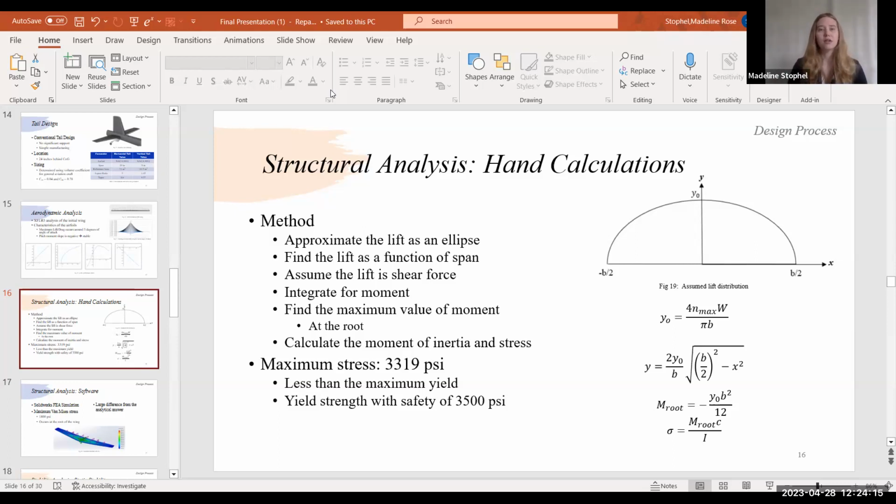We didn't account for the stress concentrations that resulted from the cutout in our PLA wing to mount our servos, and that is ultimately where the wing failed. It was not only the anisotropy of the layers of the PLA, but on top of that, we had a cutout, which was a corner and a smaller area overall. That's where we ultimately did not account for it in our structural analysis.